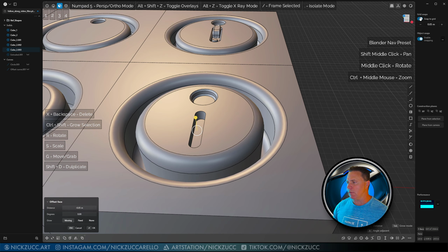And we're going to use what is called a patch. A patch will allow you to take an open surface like this and fill that hole with new geometry. Now, because I selected edges that are on this actual geometry and they're not these curves, it's not going to make a separate object. It's going to try to patch this thing and join it all together and make it into a solid right out of the gate. So we're going to tap F and do a search for patch. Once we find that, you can see the hotkey for that is Shift J. If we just hit enter, it's going to go ahead and give us this.